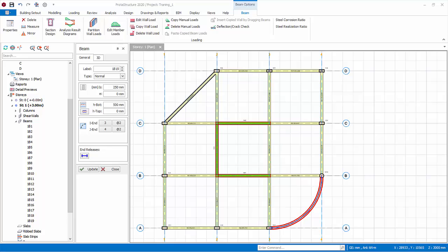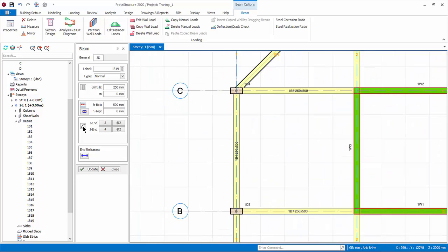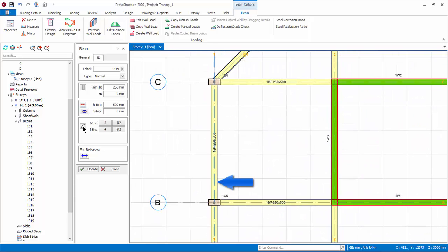We will now create some secondary beams here. Deactivate the curve beam icon to change it back to straight beam. Secondary beams can easily be inserted using the Smart Snap points, without having to create axes. Place the cursor on the edge of the primary beam, not the middle. Notice that snap points on 0.25 L, 0.33 L, 0.5 L, 0.67 L, 0.75 L will be shown, when the cursor is placed on the beam.